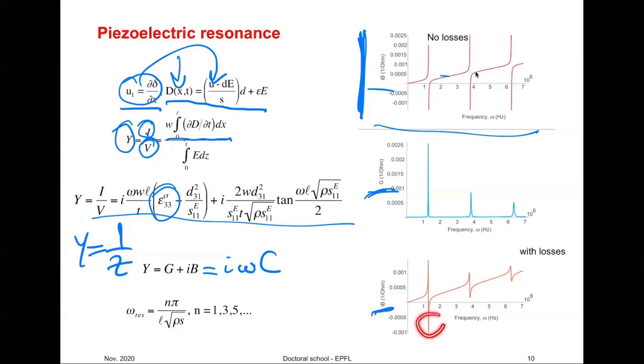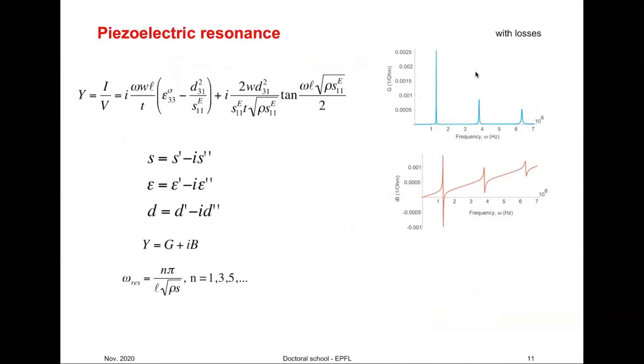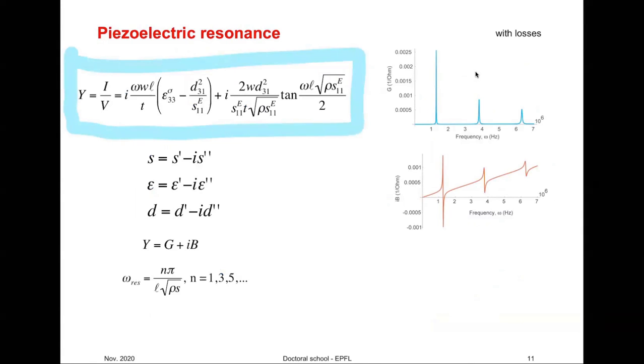What we have here is the consequence of the piezoelectric effect, which at mechanical resonance, due to inhomogeneous stresses through the direct piezoelectric effect, gives us a lot of charge, and it looks as though capacitance becomes negative and goes through singularities, but that's just an effect of the piezoelectricity. So what you can do if you are working with resonance is take this really simplest example.